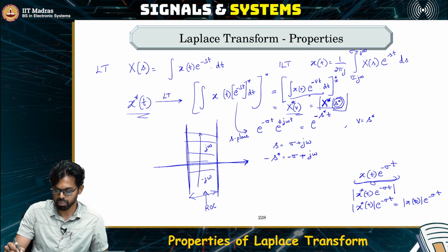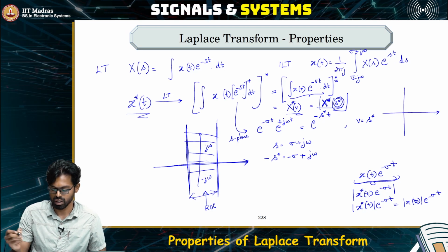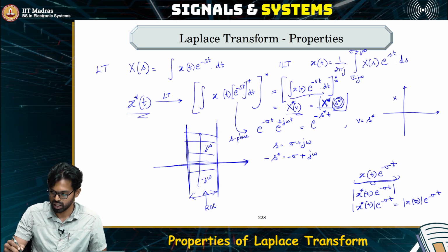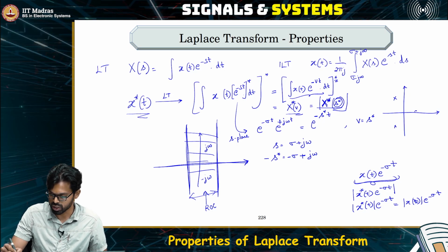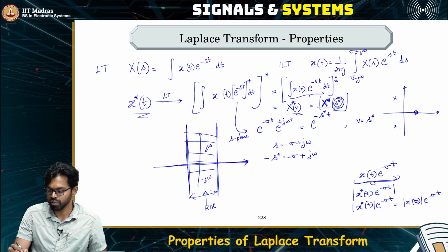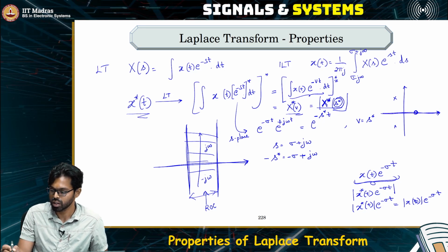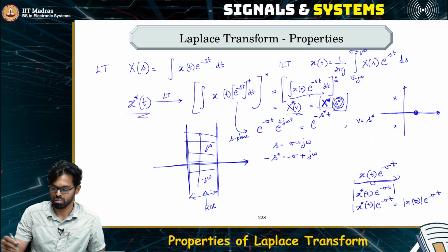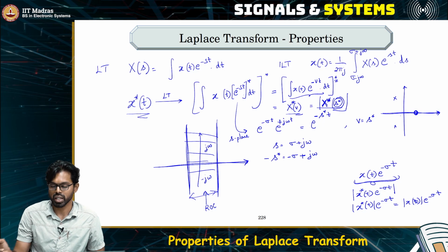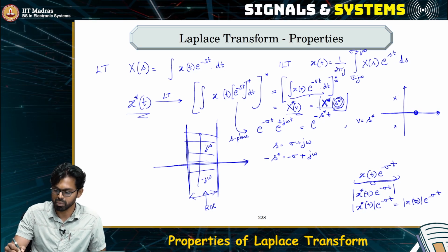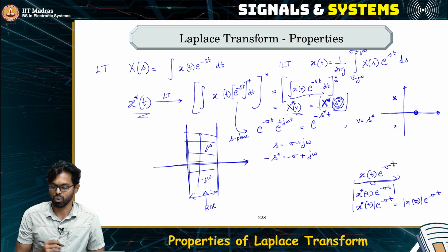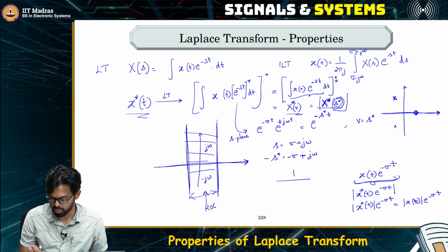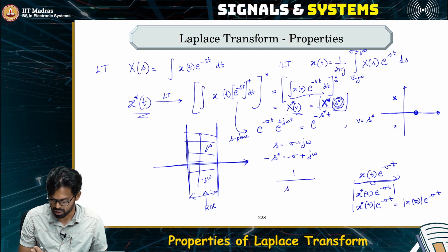So when we plot the poles and zeros, then we see a difference. Let us say now we are plotting the location of poles and zeros, and let us say there was a pole like this and there was a zero like this. Now for real values, nothing changes, because the conjugation operation does not affect the real values. Now if something was complex, let us say we have a pole which looked like 1 by s plus a.